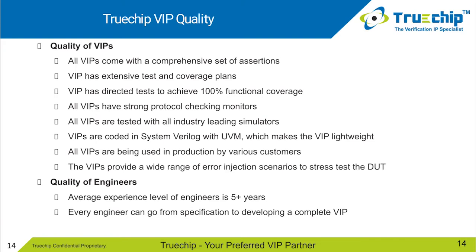These are VIP qualities. All VIPs come with a comprehensive set of assertions. VIP has extensive test suites and coverage plan. VIP has a dedicated test suite to achieve 100% functional coverage and strong protocol checking monitor assertions.